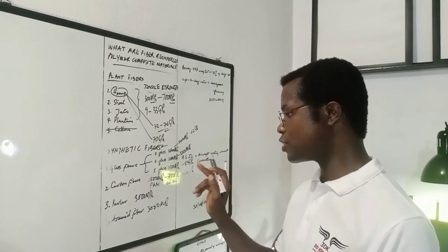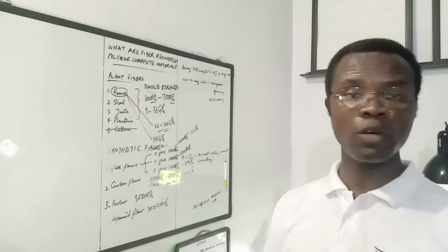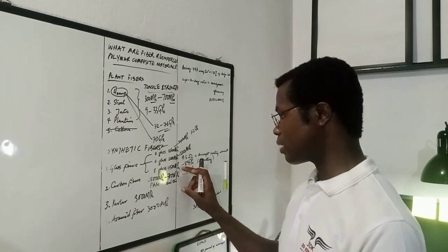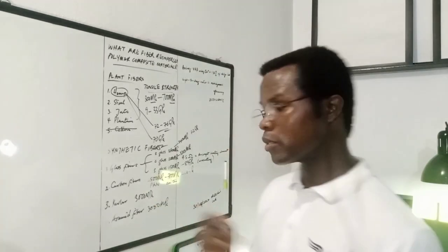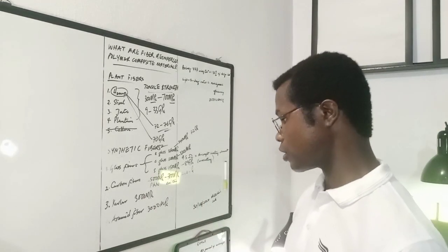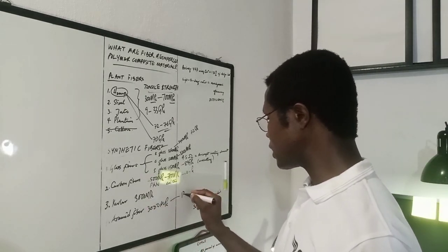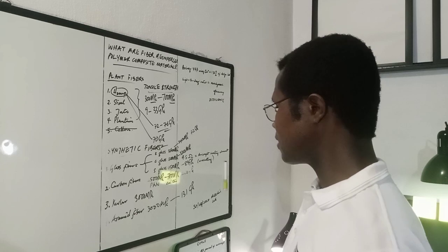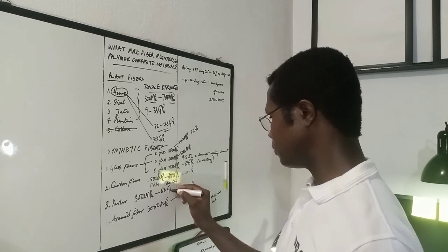A lot of high-end applications that could be done with glass fibers, S-glass in particular, people just go in and say, let's go with carbon fiber, not realizing that there are variants of glass that have impressive numbers but are very low cost, relatively speaking. That's a very big advantage, particularly if it's for a manufactured product. Aramid fibers have a stiffness of up to 131 GPa. Kevlar fibers are on the lower end, around 60 GPa for stiffness.